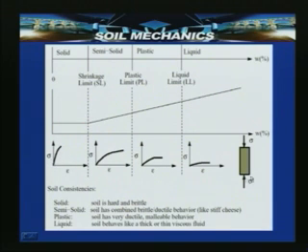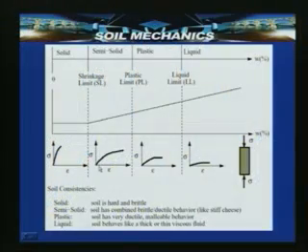For the stress strain behavior, suppose you take a sample which is pressed with a compressive stress sigma, and with an axial strain epsilon. The soil exhibits a brittle behavior when it is hard. During the semi solid state, the soil has combined brittle and ductile behavior, like a stiff cheese material.